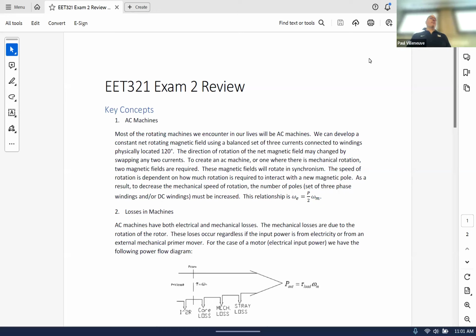And I say this because over the week right before break, they brought in some ECE candidates because they're hiring for a power position. One of the candidates, she was doing her presentation and she mentioned a lagging power factor. Then when she did her S calculation, she came up with S first and she wrote a positive angle. When somebody said, hey, that's a lagging power factor, why does S have a positive angle? She couldn't explain. This is somebody with a PhD who is looking for a job. She couldn't explain the concept of leading or lagging.